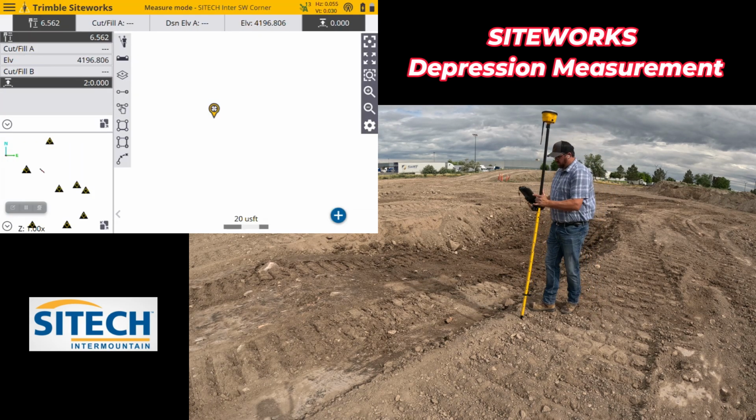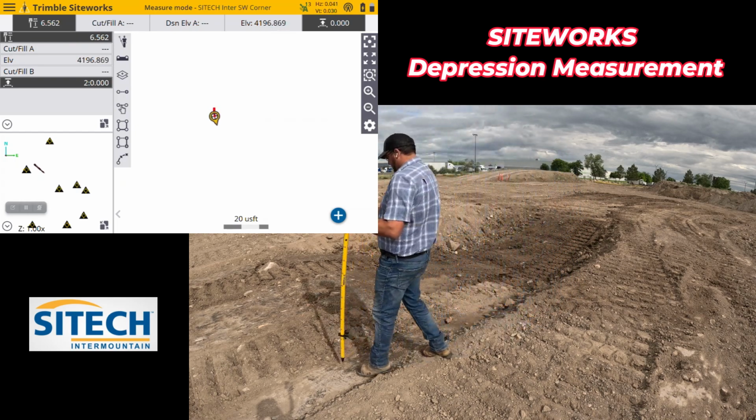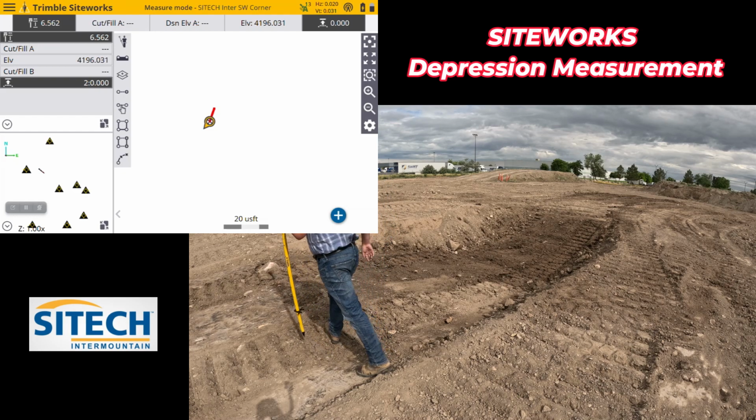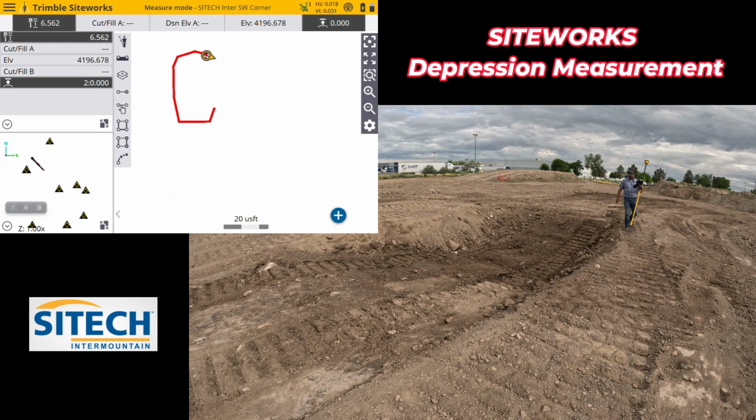Now it's a matter of just walking around and shooting all the highs and lows and actually capturing the outermost point of what I want to get the volume from. Remember, as you do this, it's going to gather the highs and lows if you're going to run it just as a depression. There's a couple different ways to do the stockpile measurements in the report. I'll show you how to do that here in a minute. Once again, just creating an outermost point. I'm going to run right along this ridge right here.